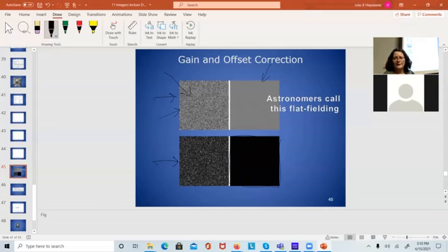And so our idea for a PUF was we were going to just take a camera and put a cover for the top of an IC on top of it, tape a dead SRAM to the top of the lens, which is what we actually did, and put the camera in the dark and take images. And yes, we got randomness out of this.